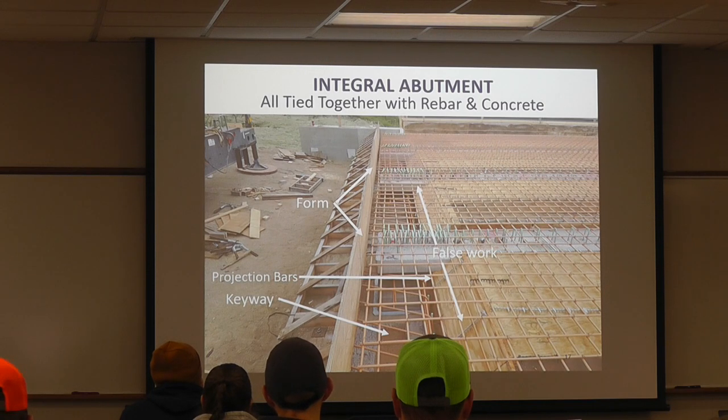Okay, so again, and actually something like this, I should back up, the keyways on these integral abutments. There's quite a bit of force that's going on there. And so the keyway is important. It's not just, oh yeah, kind of nice to have. There's a lot of load that's getting transferred, including through that keyway.